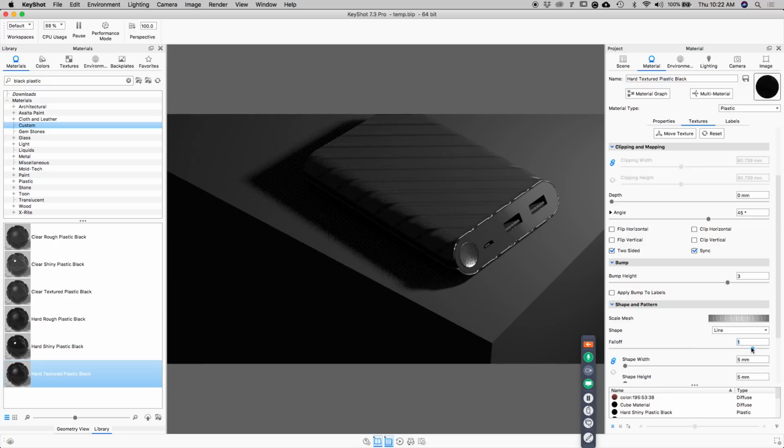So the key here is I'm going to set this to a very low value, say 0.2. And that should give us a fairly crispy bump edge. It's subtle here, but we'll see it in a bit. I just wanted to call that out, because if this is the first time you've used this texture, this little falloff guy can be key for making a bump texture with the mesh procedural look decent.